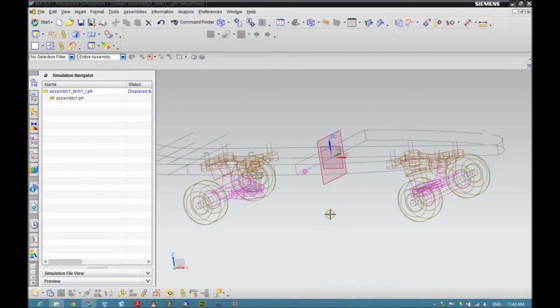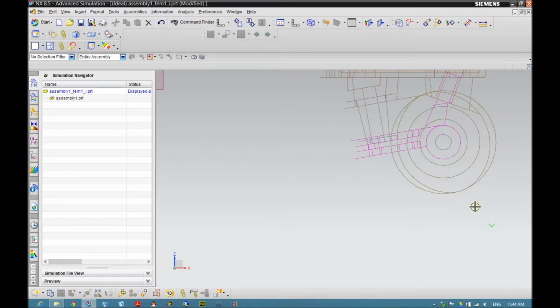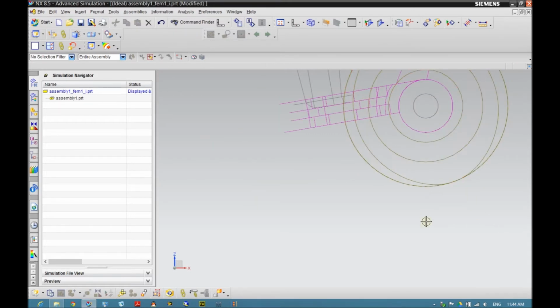Okay, next we are going to split the wheel. So you might ask, why do we have to split the wheel? Because we already have 4 wheels, and we don't need to actually split the wheel itself, because, well, the answer is, when you do the mesh, you're not sure that you will get a node or a line of nodes exactly on the bottom of this wheel, because when you do the simulation, you want those nodes to be exactly at the bottom of the wheel.